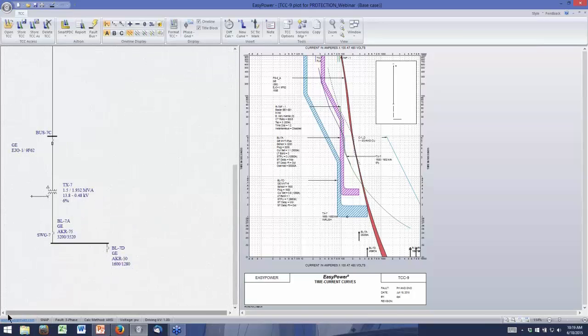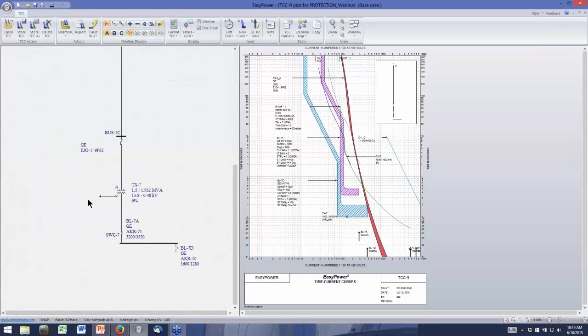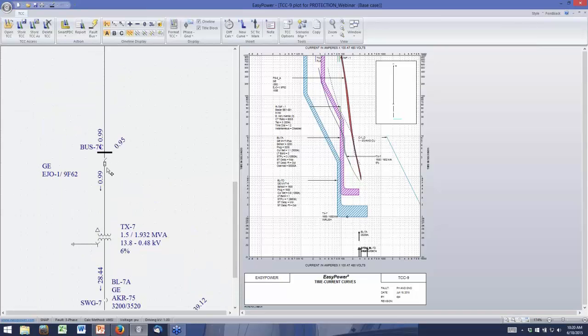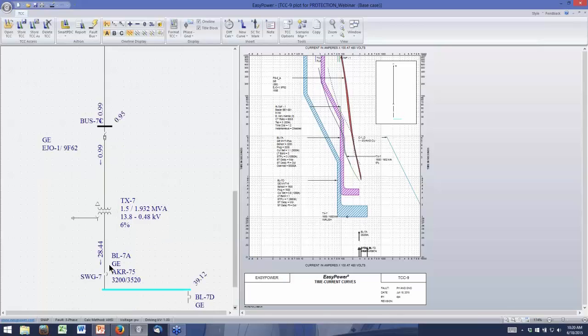One of the things you can think about is, if I look at my half-cycle fault current down here, I have 39,000 amps of fault current, of which 28,044 amps are coming down through the transformer. The rest is motor contribution. That translates to 1,000 amps going through this into the primary of the transformer for a secondary fault.